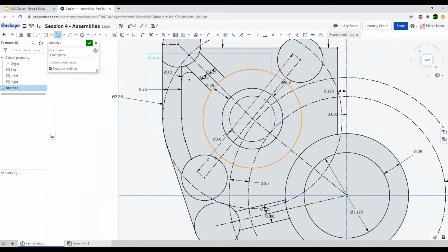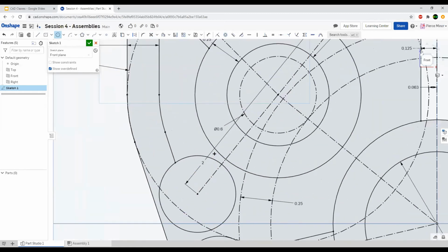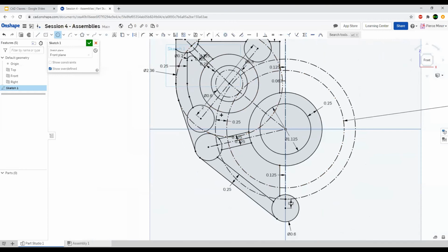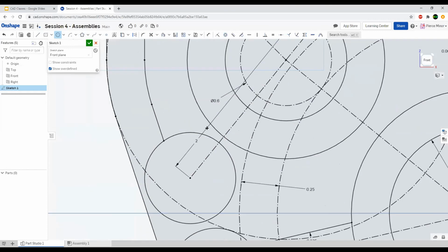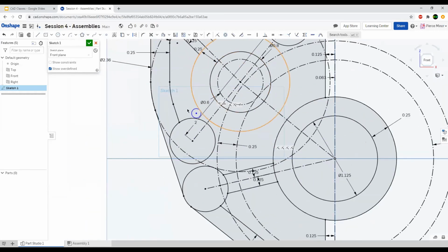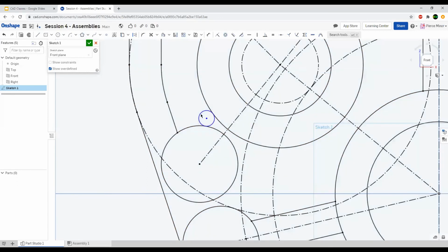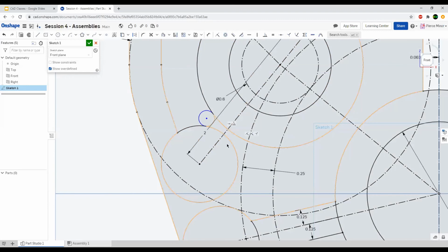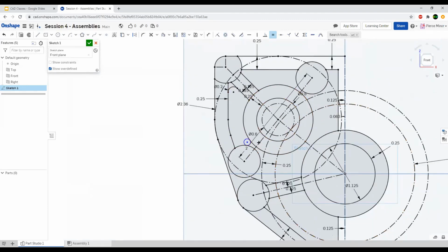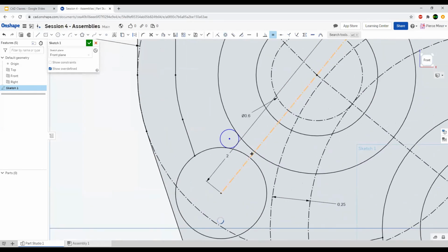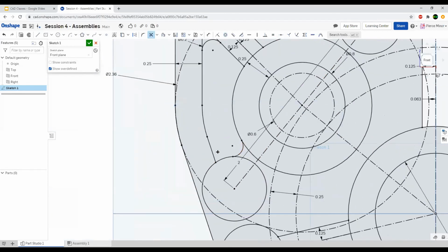Here's the reason why I said we didn't need to have a line here or there that connects that to that or there. If I put a curve in, look, there's so much space, and this is smaller than that one. So I want that to be tangent to that circle, so use tangent. And then since that's still resizable, I'll just set these equal to each other. And then once Onshape finishes loading, all right, so I have that, I can just trim it. It's done.